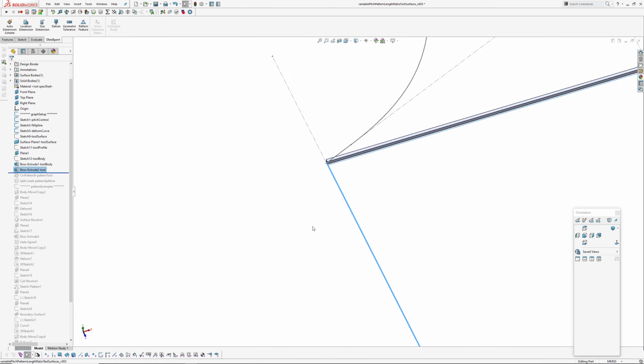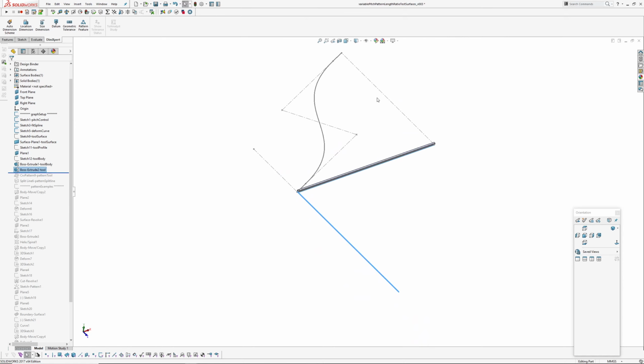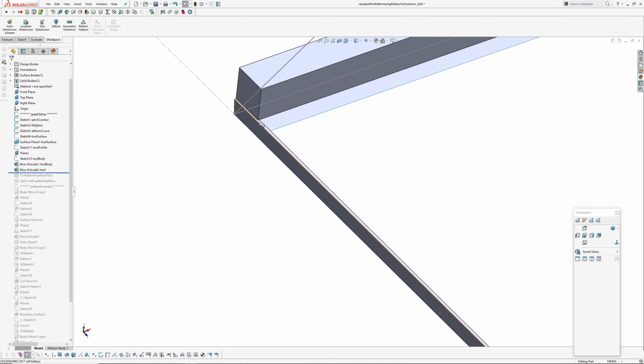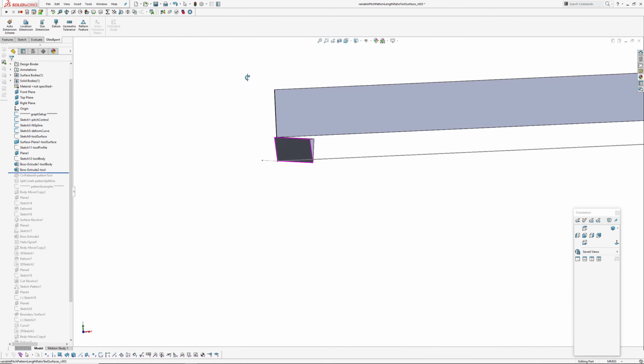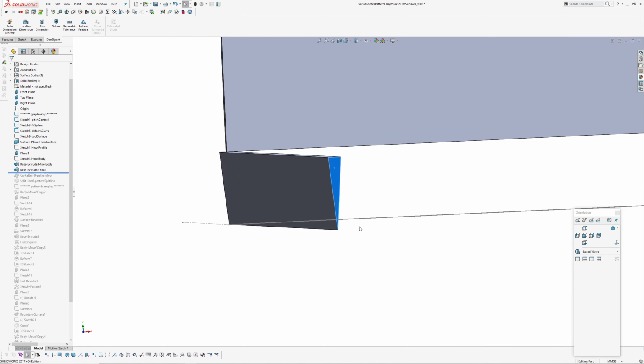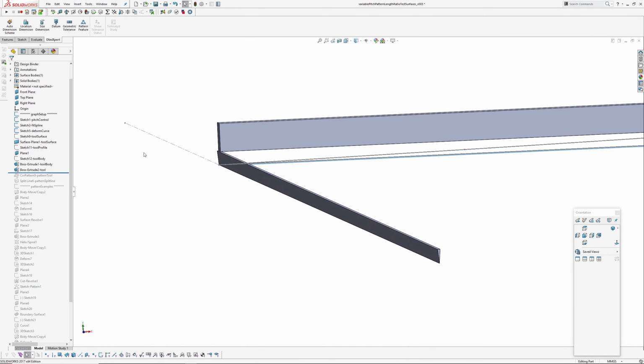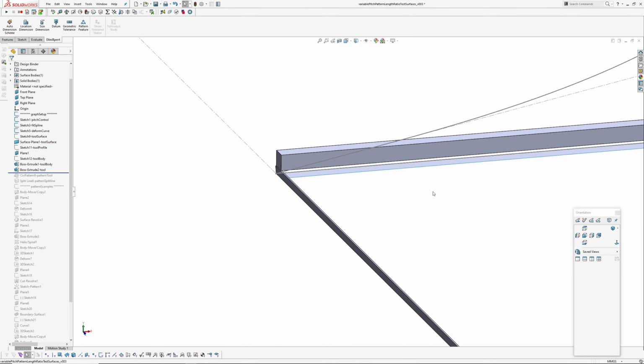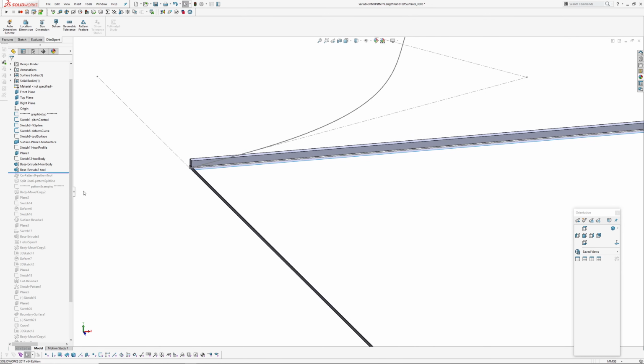Now the tool, when you extrude it, has to be longer than the y-axis of your graph, which will become obvious in a second. So I've made that 110 long. So that is basically a wedge. Okay, and on the wedge, make sure, this is critical, merge result is on and it's merging to our tool. So that way when I pattern this, we end up with a single body. We don't want to end up with a whole lot of separate bodies.